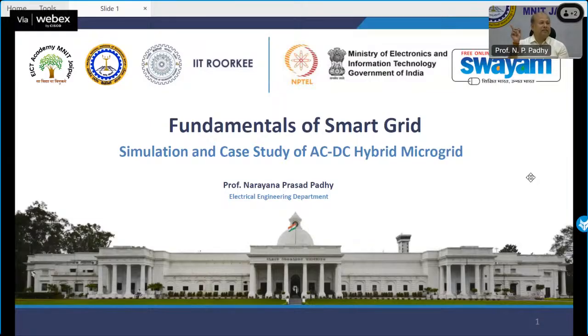Only the person sitting next to the substation will experience the tube light joy, but others will have normal bulbs. The reason being, if it is 230 volt single phase at the substation, 11 kV to 400 volt, 3 phase, single phase close to 230, and that keeps on going, the last one will get closest to 210 to 250.